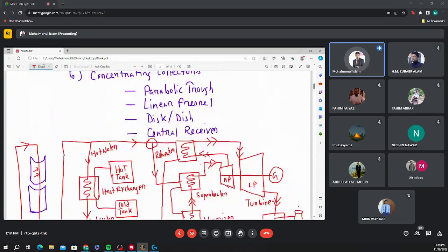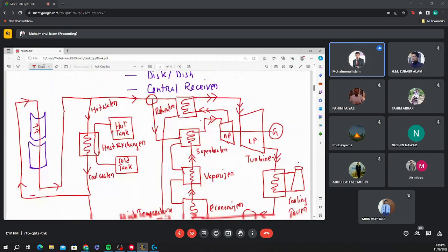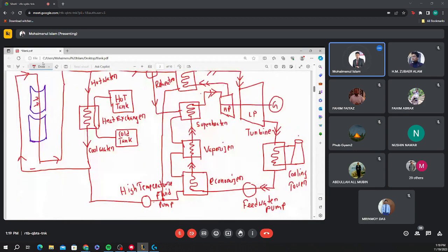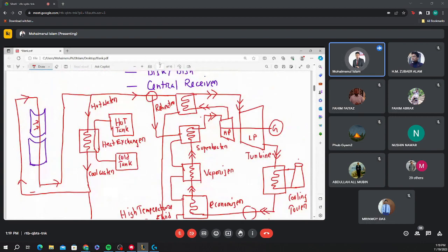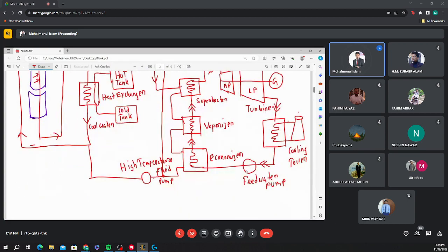And also we can use that superheater, that superheated content. So with that terminal, the hot water coming in superheater exchanges the heat. Again, additional, the more heat content it has, so you need to add it into the vaporizer section. It will help you to vaporize the condensated water. Also, you can use the remaining thermal heat content into the economizer to preheat the overall water.